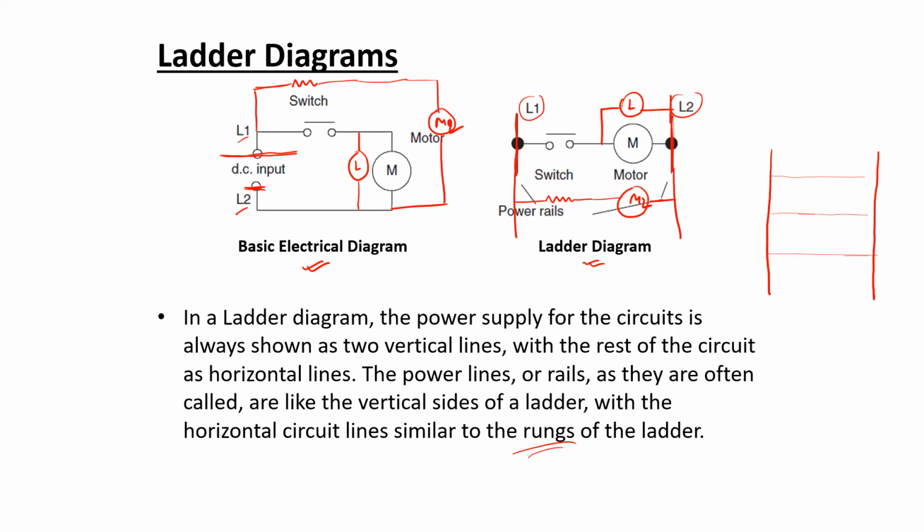But basically, using the ladder diagram, we are representing, in the case of a PLC, how the CPU should execute different instructions. And if you remember from the previous class, both the input modules and output modules were separated from the CPU. Do you remember why? Yes, sir. So to electrically isolate the circuits so that the input or output cannot damage our CPU.